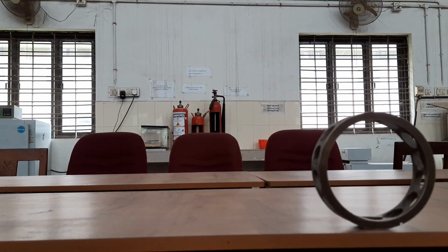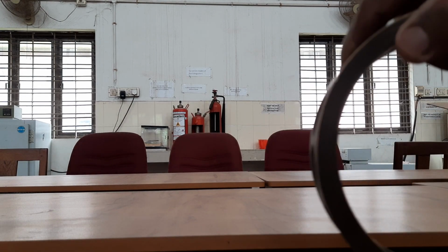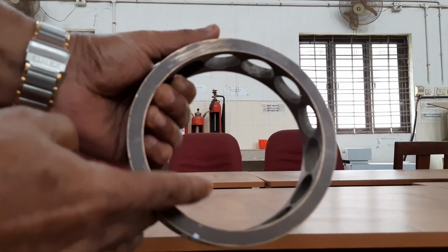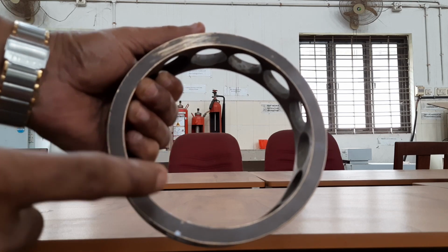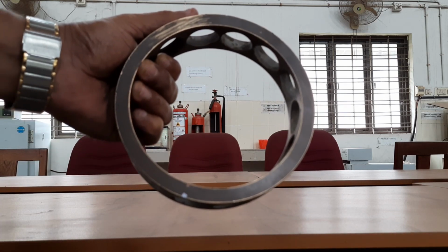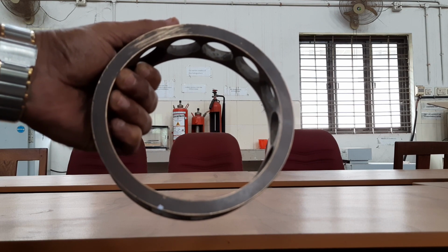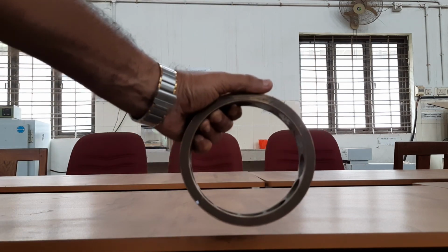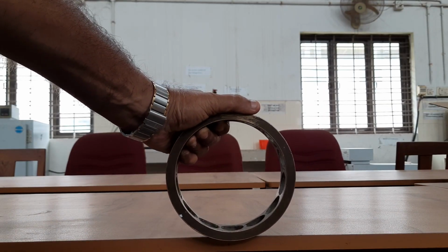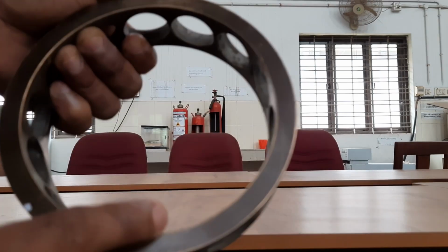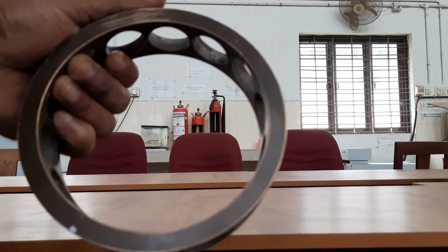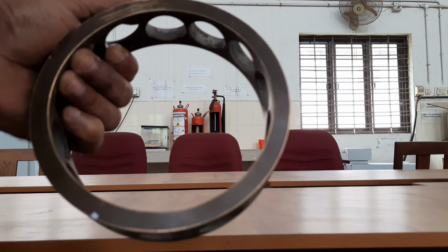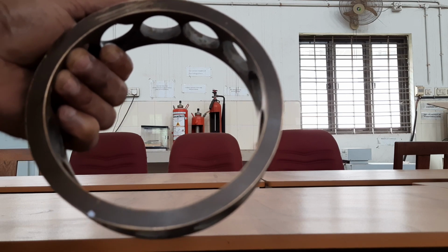Agreed? Now, the point can be inside the rolling circle. If the circle is a disc, this point can lie inside the circle. The path traced by the point inside the circle is called an inferior trochoid. Agreed? The path traced by the point outside: how does the point lie outside? It can roll on an edge, just like the wheel of a train. So the point which is protruding outside will trace a superior trochoid. Agreed? We are going to see how the trochoids and the cycloidal curves are drawn. We will see it later.